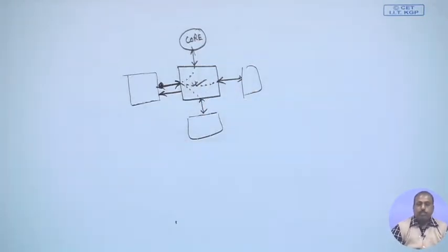So, there has to be a decision module which will look into the destination address of the packet that has arrived, and accordingly take a decision to which port this incoming packet should be put into. We have a number of input ports. Every channel, or every primary input that we have, goes into one input port, or we call it IP.